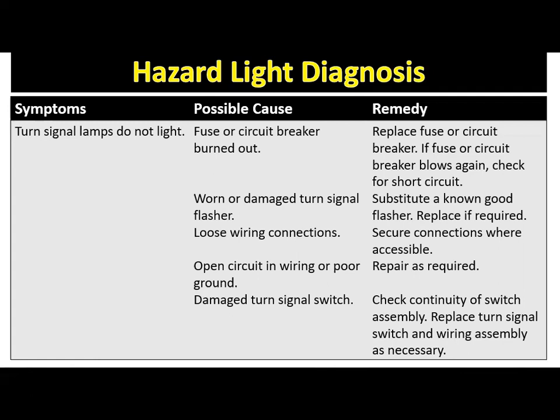If you hear that audible sound, then the flasher is good. If there is no sound, total silence, then you have to replace the flasher. Then secure connections where accessible, repair as required. Check continuity of switch assembly, replace turn signal switch and wiring assembly as necessary.